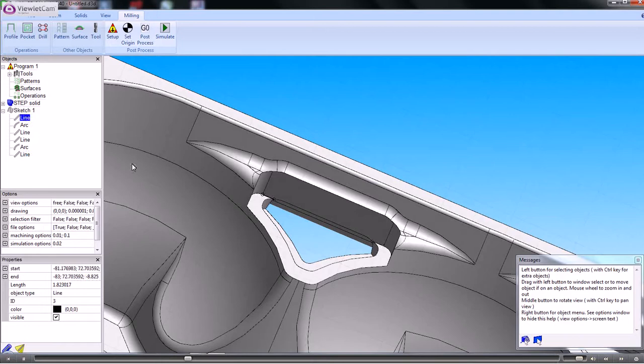So if we wanted to modify the line just over here such that it meets the end of the line there, we click on that line, and under the properties window here it gives us a start point in X and Y. So if we just use Control C to copy that X position, and then we go to the end line there and we go to the X value there and do Control V to paste, what that does is that it modifies the end of that line such that it's coincident with the start point of the other line.